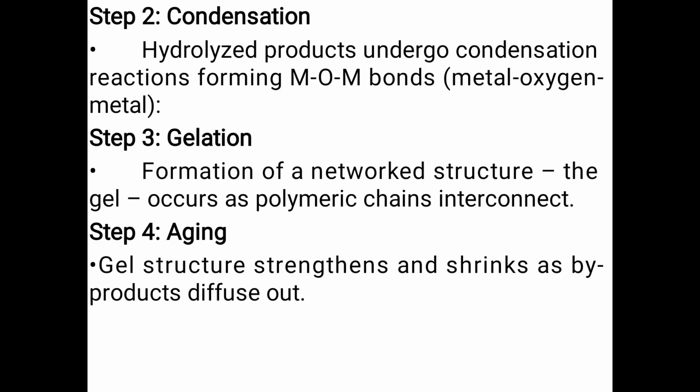Step 3 is the gelation. This is the formation of a network structure, that is the gel is formed, which occurs as polymeric chains interconnect. Step 4 is aging. Here the gel structure strengthens and shrinks as byproducts diffuse out.